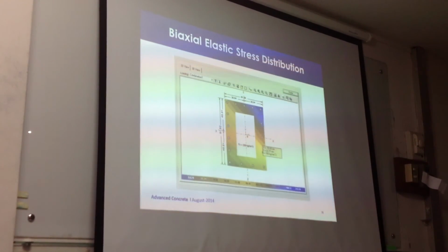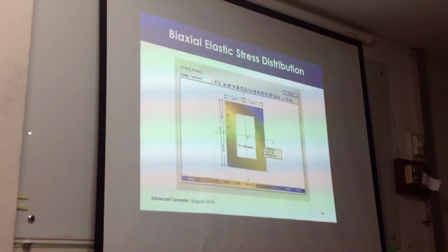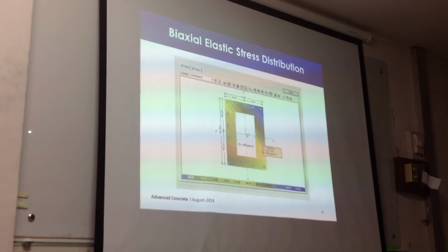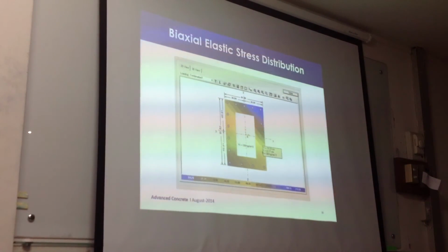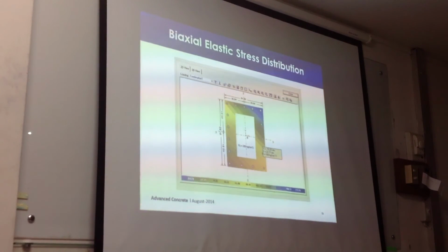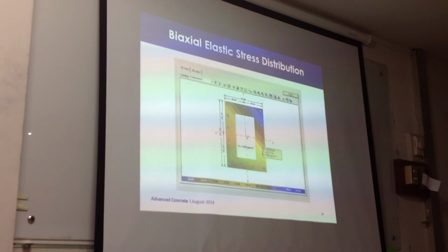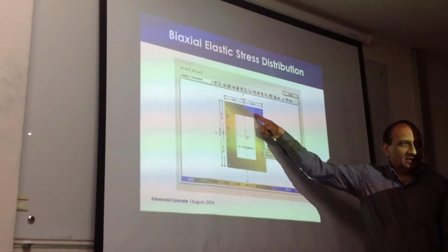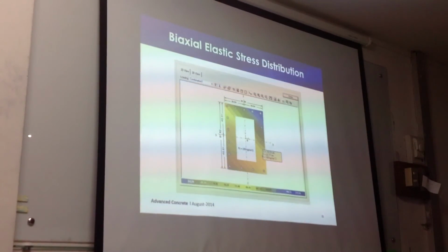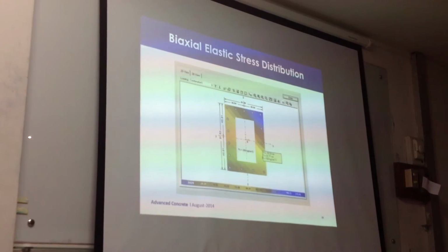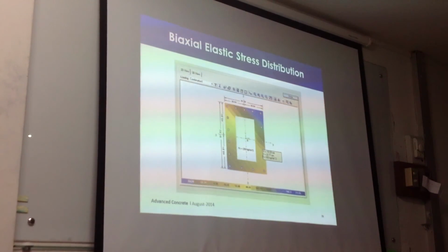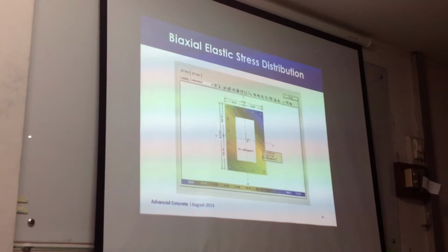Please remember this. From actual load, you can calculate the stress and you can calculate the strain, which will not be the same as the strain that you assume and you calculate the stress and calculate the load. So one way, I've shown you both paths, right? One path is apply the load, it will create the stress and it will create the strain. These are always called elastic stresses and elastic strains, right? And they are only valid if the cross section is deforming linear elastically, correct? If the cross section is non-linear, which we know is non-linear, that will not be true.